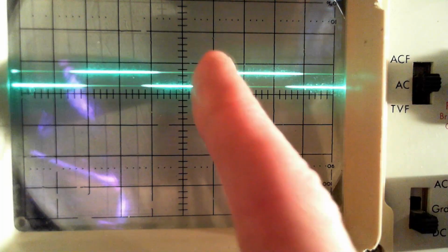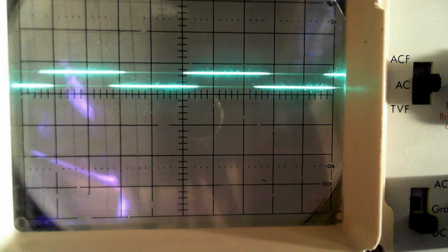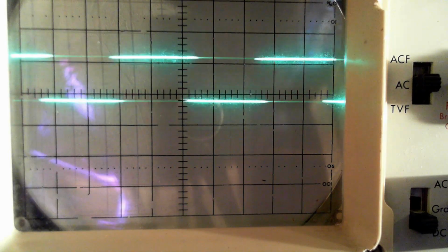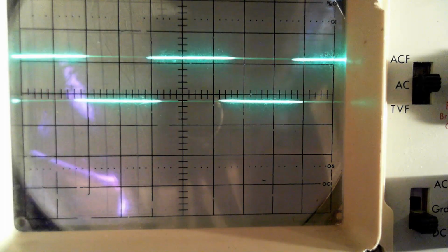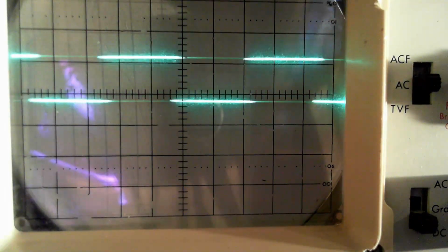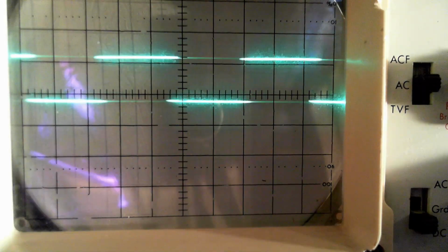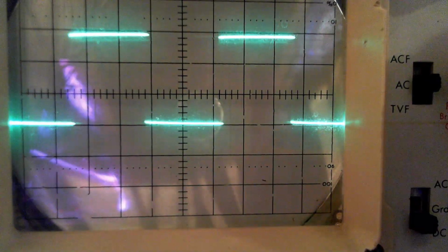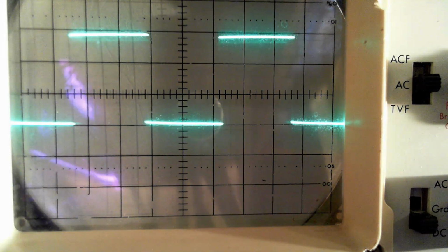So now to get an accurate measurement here, you have to multiply by 10. What I'm going to do is I have a 10 dB pad and I'm going to take it out on the output. Okay, it's drifting because it's below the trigger level of the scope right now. When we're supposed to be on 0.2, which we are, but what if we go to 0.1? Adjust the trigger just a wee bit. Okay, so now I'm much closer to what they're saying in the manual.